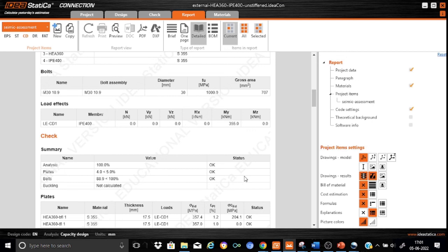So these are very important procedures when we need to go for a partial strength or a semi-rigid connection, because there are specialized versions. In fact, for big structures or very critical industrial structures, we need to qualify the designed joint either using a series of tests done in the lab, or using software that has successfully verified numerically the established databases available from various valuable projects, and then use the same for our specific joint, and through the numerical analysis and a proper loading procedure we'll be able to check the acceptability of the designed joint.